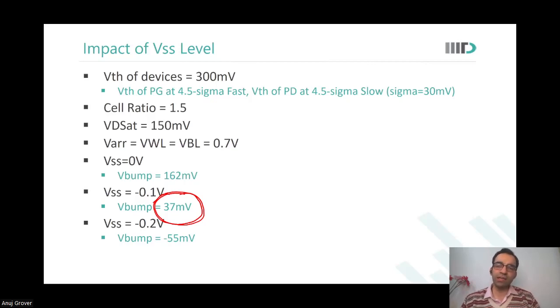When we go to these negative voltage levels, while over here I'm doing the analysis at 0.7 volts, suppose I have to generate this negative voltage at 0.7 volts. How would I generate that? I would do some charge coupling. I would put in some capacitors. I would toggle those capacitors in a particular way, so we'll look into this detail later also. We will generate some negative voltage on the fly.